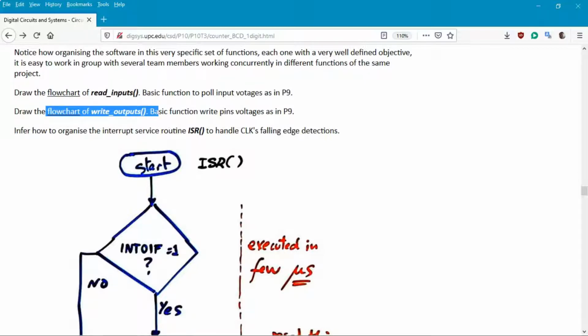Remember, first of all, we read all the port to save the information of the bits of no interest. And then we, at the same time, clean the bits that are rewritten, okay? And then we shift every single bit to the right port position, and then we write all the bits of the port. We do that when writing.